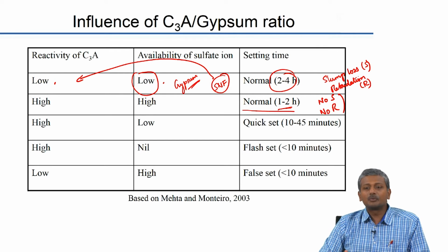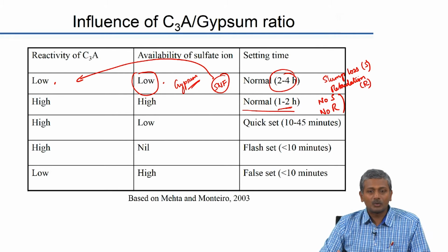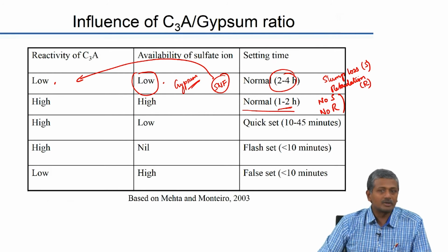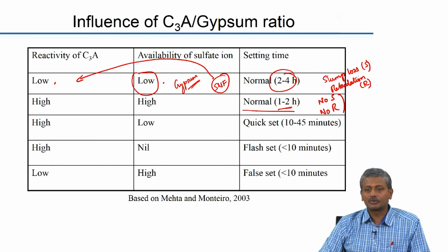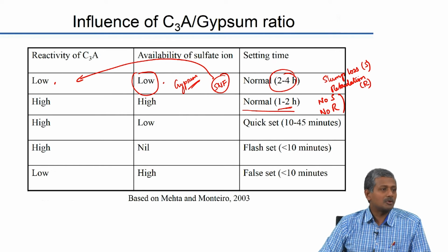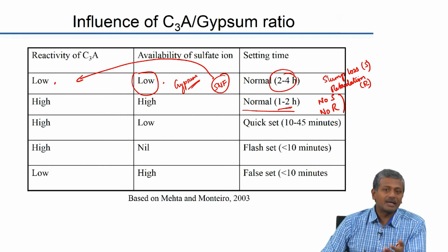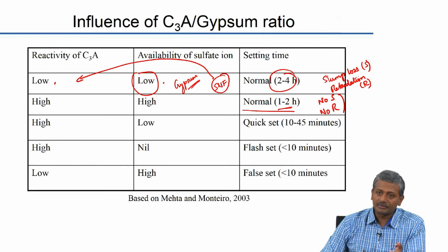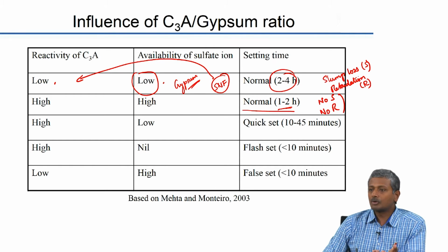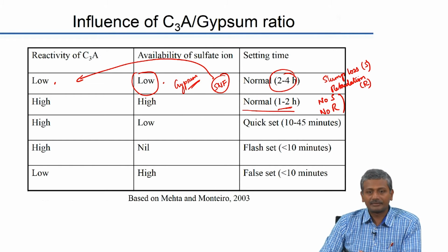Now that gives you much lesser time for playing around with your concrete in terms of workability, open time and so on and so forth. So that is something you need to keep in your mind. So for example, if you are looking at ready mix applications, this may be a useful combination to use if your travel times are less.